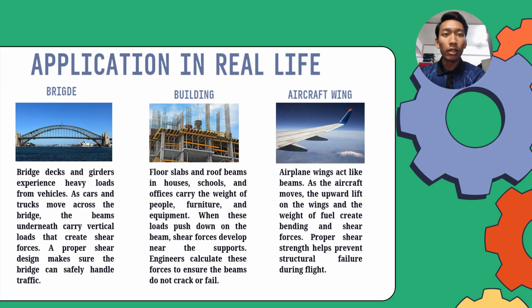My name is Mohammad and I'm going to explain about the shear force of a beam in real-life applications. The first one: bridge decks and girders experience heavy loads from vehicles. As cars and trucks move across the bridge, the beams underneath carry vertical load that creates shear force. A proper shear design makes sure the bridge can safely handle traffic.